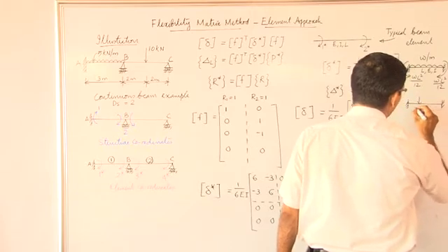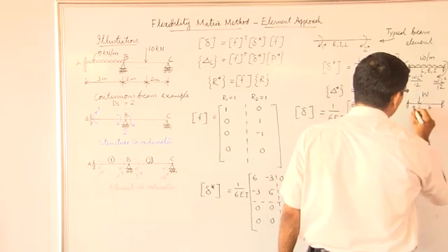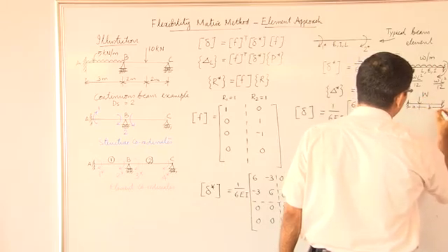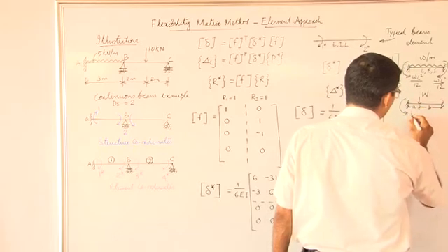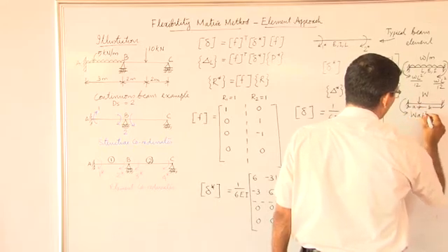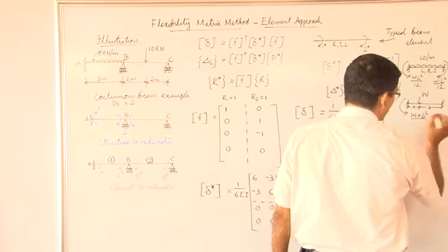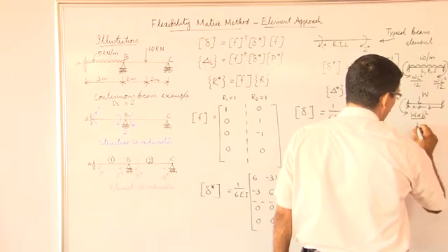say eccentric point load, capital W with this is A and this is B. This moment is equal to W A B square divided by A plus B the whole square, or if A plus B is equal to L, we have L square.